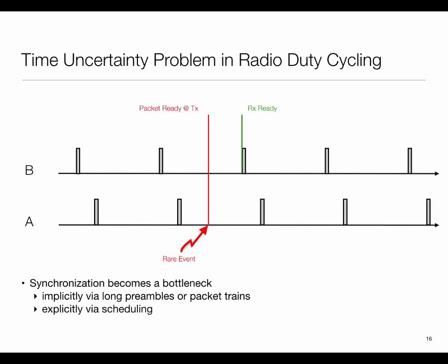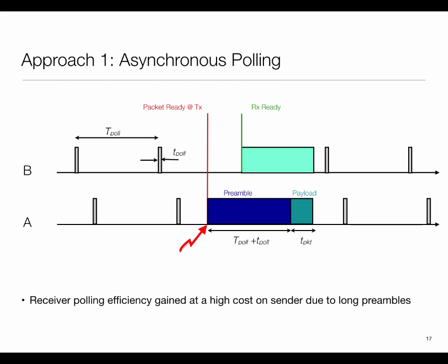So I have node A, I have a node B, and node A is periodically checking for events happening, and whenever it has an event to send, it is going to send it. But the receive side is waking up periodically, and it doesn't want to miss that event. So to do this, what could be done is the following: when A has an event and starts sending it, it starts sending the packet, and it stays online until it knows that the receive party would have woken up.